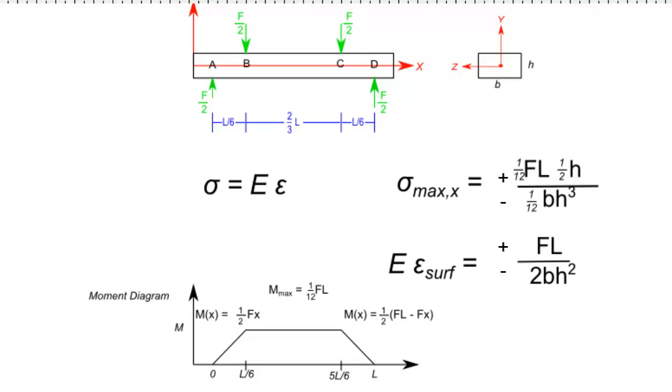The slight drawback to 4-point bending is that it should be carried out by measuring the deflection of the beam's midsection. This requires a slightly more complicated setup to measure the deflection. However, as it's not very difficult, the rewards are definitely well worth it.